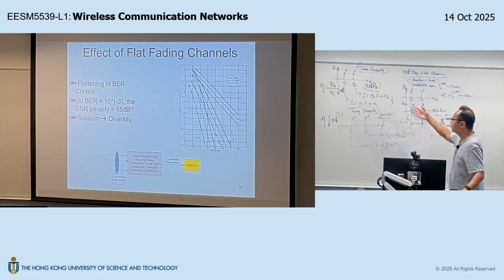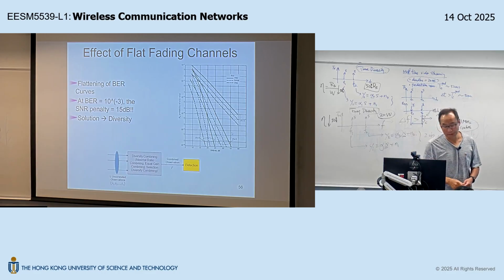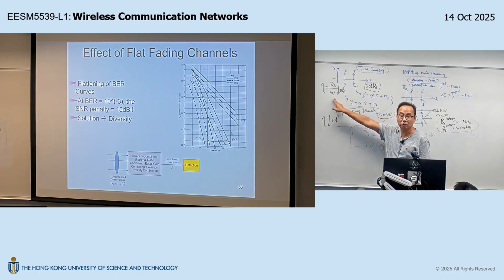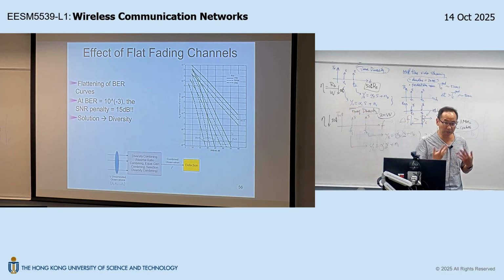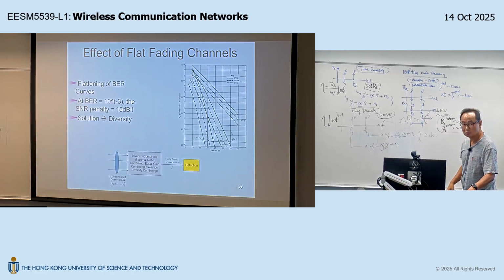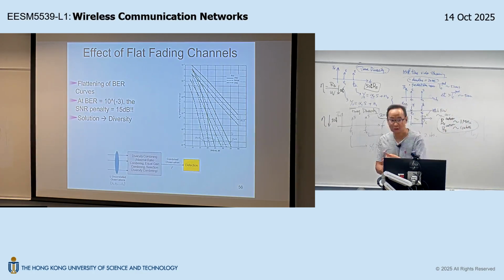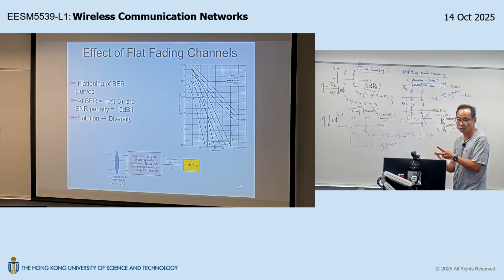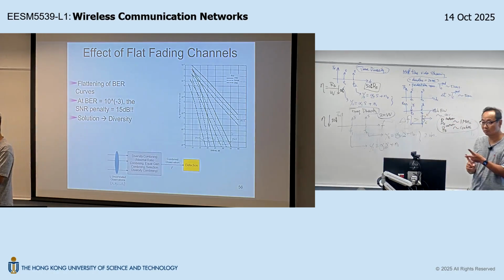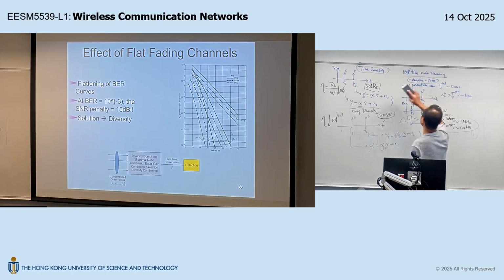Now, it seems that time diversity and frequency diversity are not that ideal, because you need to pay a cost in performance, in the spectral efficiency, right? You need to suffer a 50% loss in spectral efficiency, and that's not too good. So do we have a third way to create diversity observations? We have explored time. We have explored frequency. What are the other resource dimensions we can potentially make use of? Space, right? Very good. Space. So let's try space.